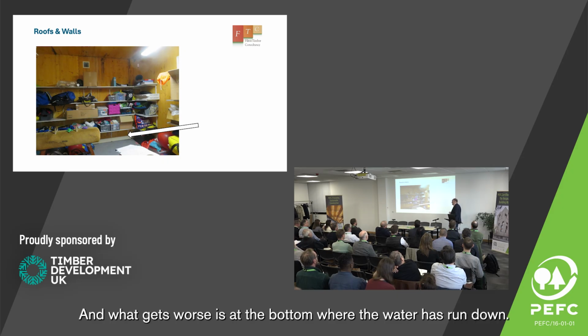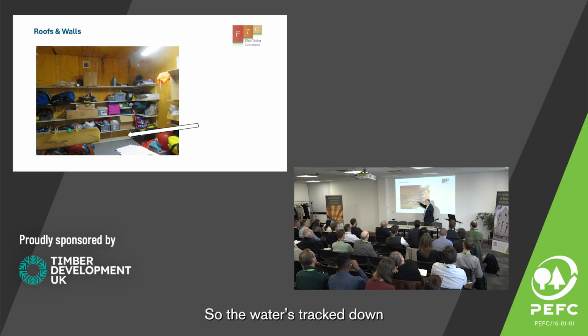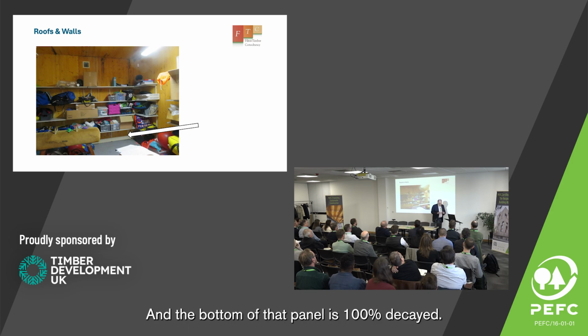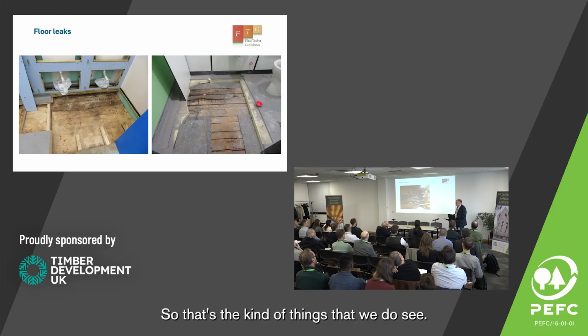And what gets worse is at the bottom, where the water's run down, I've got CLT, this one was actually at ground level, the base of ground level, so the water's tracked down and it's gone 7, 10 meters in both directions. And the bottom of that panel is 100% decayed, even though you can't see it. Okay, so that's the kind of things that we do see.